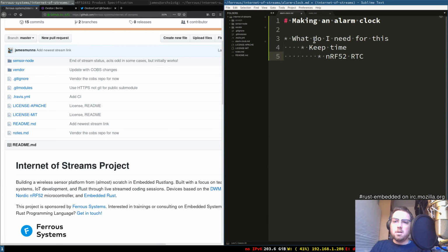But if you're counting over and over like a clock, like I'm counting every second, and over time your clock drifts, then you're going to end up losing seconds. If you're something like 98 or 99% accurate, that means you're losing 1% of your seconds in a day, or gaining 1% of your seconds in a day. And some of these clocks can be even worse than a couple of percent. They can be like 5% off, which the microcontroller won't notice. It's still happy to run like a CPU, but if you're trying to keep accurate wall clock time, the errors add up over time. If you let it go for a week or a month, you can lose seconds and then eventually minutes, and if you go long enough, you'll lose maybe a couple of hours over a year, which isn't great for an alarm clock, because that's annoying.